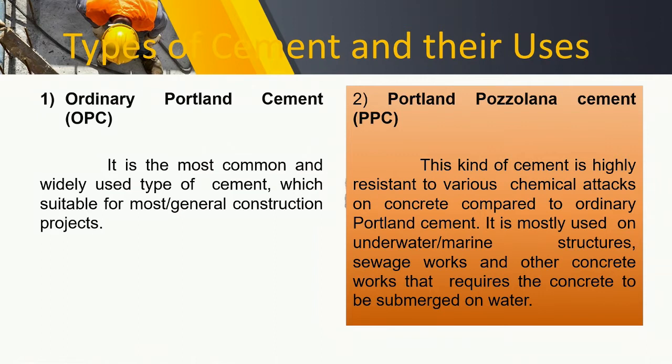And number 2, pozzolana cement, or PPC. This kind of cement is highly resistant to various chemical attacks on concrete compared to ordinary Portland cement. It is mostly used on underwater, marine structures, sewage works, and other concrete works that requires the concrete to be